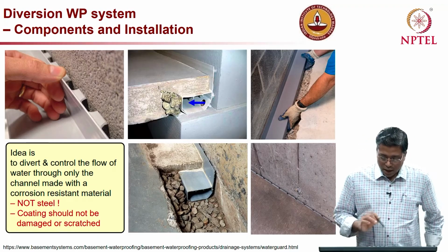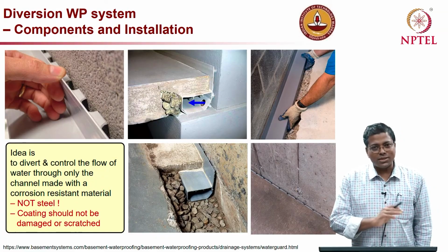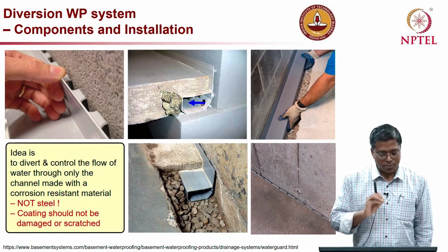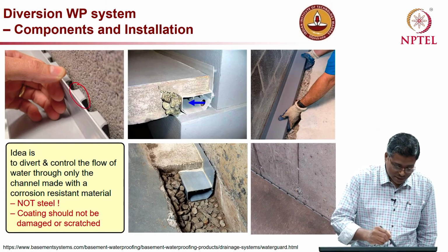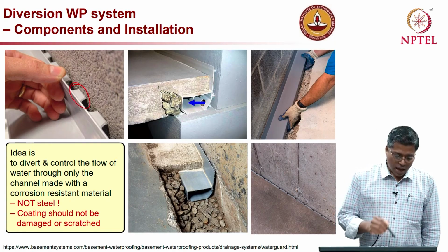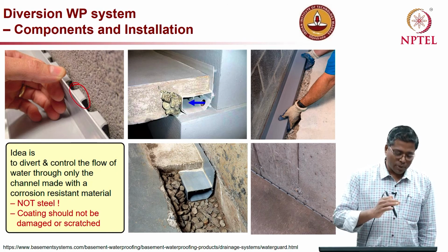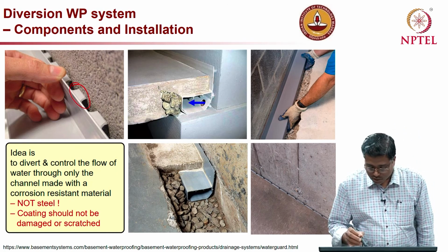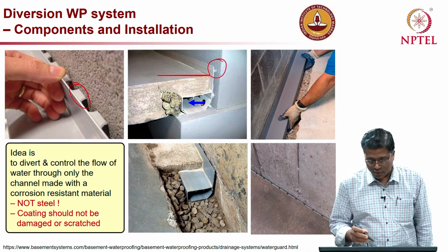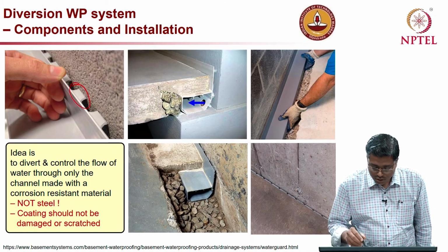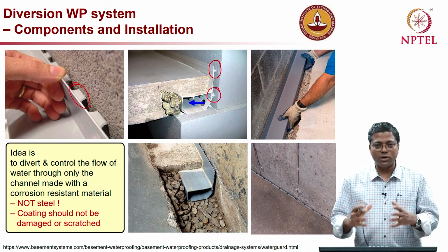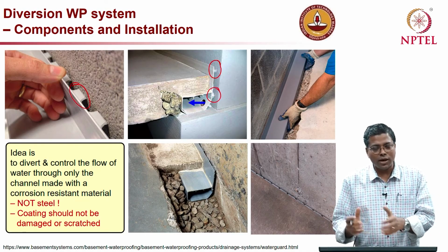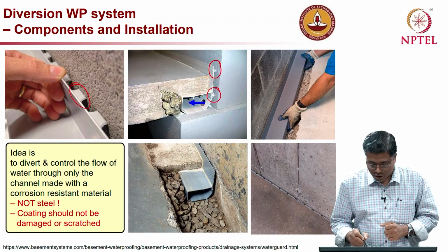Now, again here it is not just laying a pipe over there. There are some design features also associated with this. You can see here there is the spacing between the concrete and the particular element. As you see here, that spacing is very important, because you want some air space over there for the water to accumulate and then take it into the pipe.